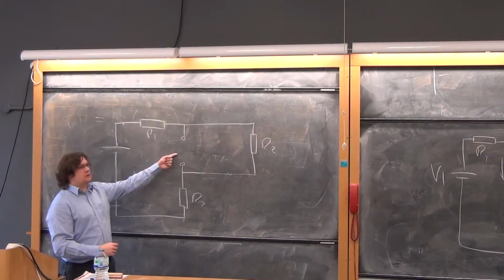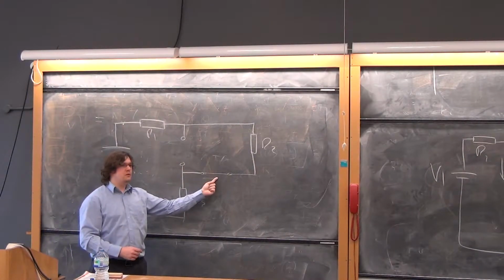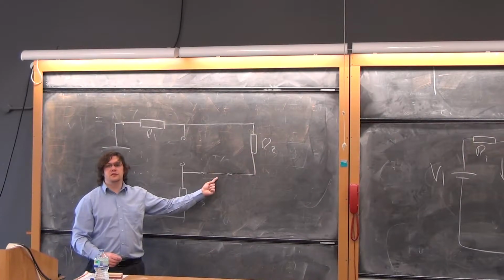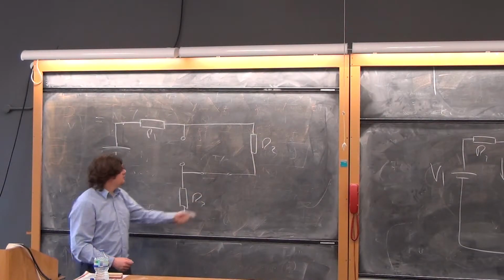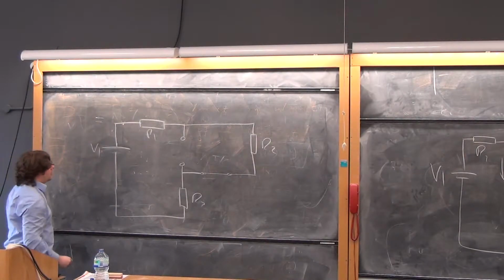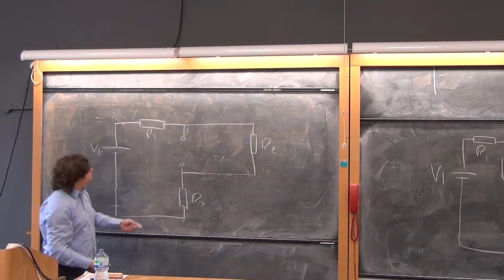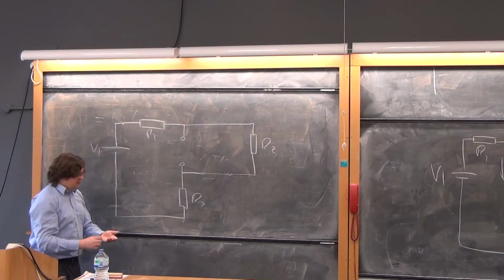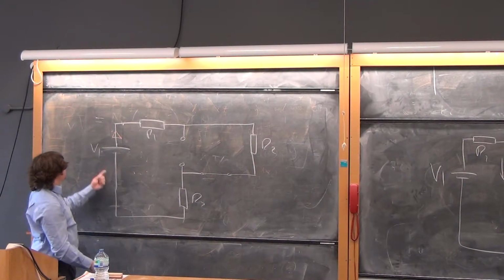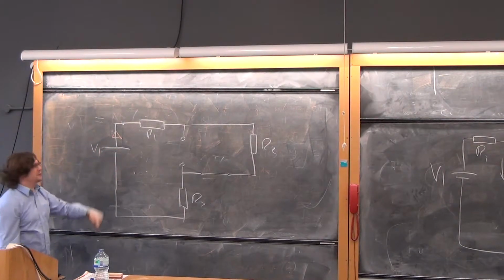So current source is gone, replaced with internal impedance, which is infinite. Diode's gone, or the voltage source which represents the diode is gone, and replaced with its internal impedance, which is 0. So then we work out this circuit, given the value of R1, and what we're interested in is the diode current. Now, just by looking at it, I know that the current's going that way, because this is positive and that's negative, and the current wants to go that way. Everybody happy with that? Yeah, good.